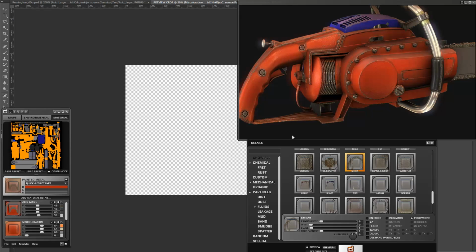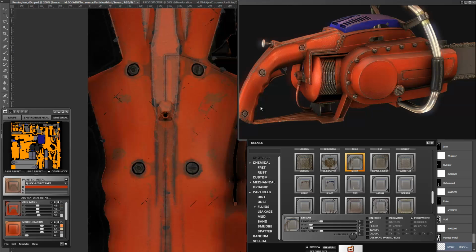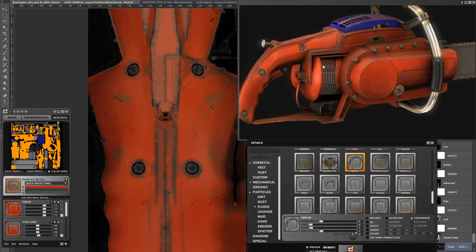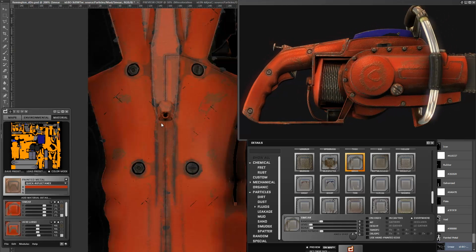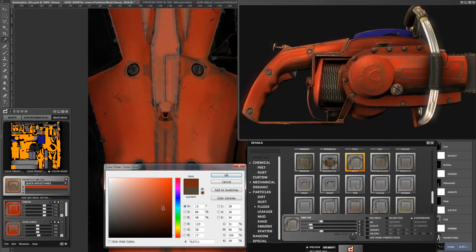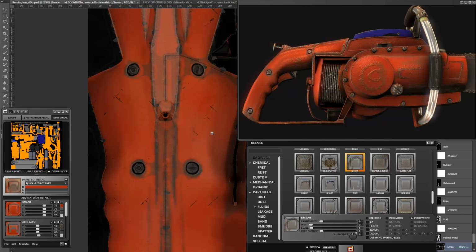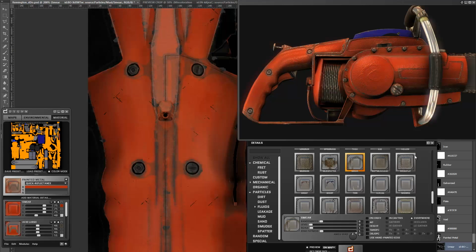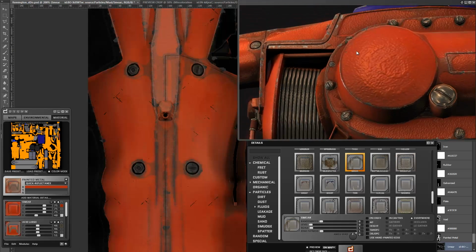and as you're gonna see in the previewer, it's gonna be a bit too extreme to start off with. There we go. The color of it is really off, so I'm gonna change it by clicking the swatch here. I want to make it almost the same color as the red below it. Just a little bit darker, just like this. I also want to reduce the height information to around 40% and preview. There we go. Some slight variations in there.